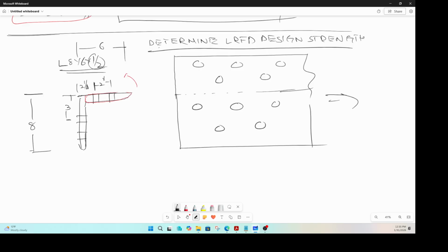Now the interesting thing is, because you're cutting it here and then turning it up and attaching it here, that leg loses one thickness in the process. So the most important thing when you unfold is to find the gauge distance between this bolt and that bolt. The gauge distance between this bolt and that bolt is pretty easy. That is just 2 inches. The question is to find this other gauge distance. If you find that, the rest of the procedure is pretty easy.